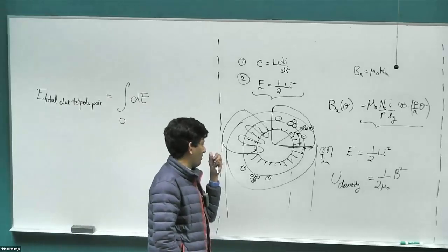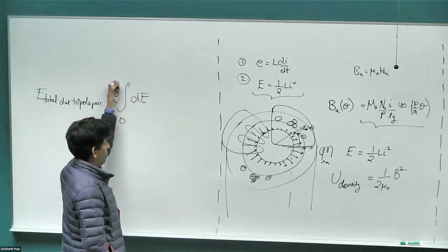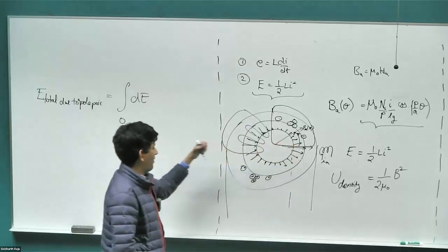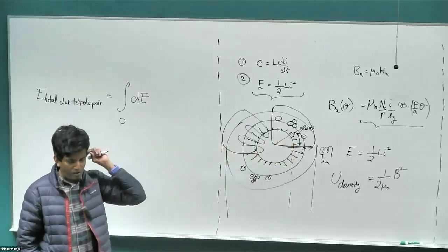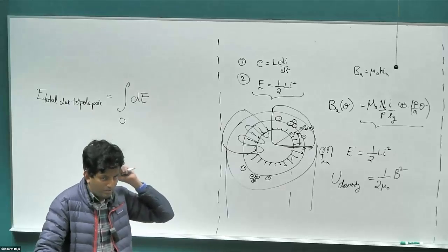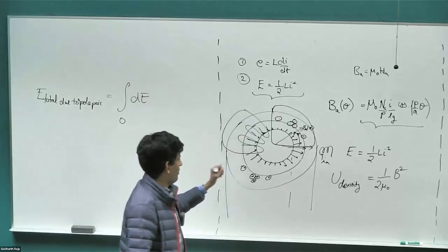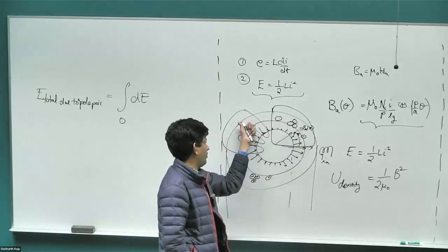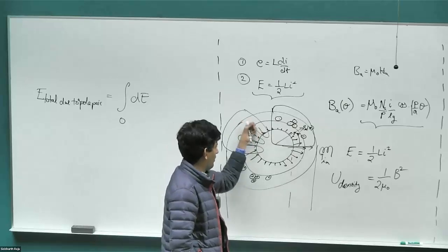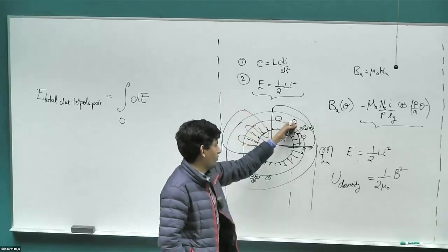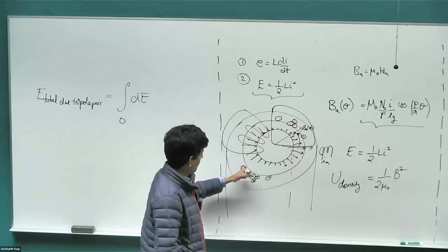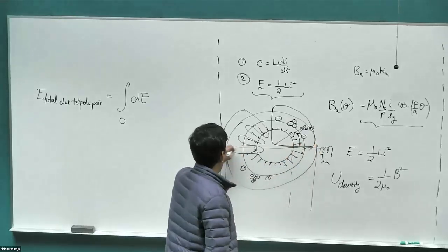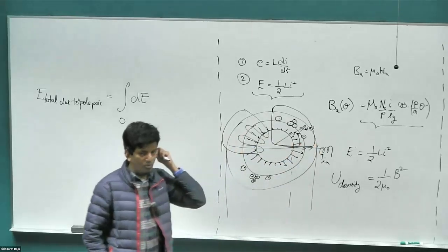Let's say in case of a two-pole motor, the integral is very obvious. I'll do from 0 to the full angle, 0 to 2 pi. If I want to do it for a p-pole motor, what would be my angle upper limit of integration? Because I just want to figure out what the energy is due to a set of coils. If I have this set of conductors coming out of the page and this set going into the page, their combined effect sets up magnetic field in the air gap, which goes in on one side and comes out of the other side. And then the other set of coils does the same thing. So all I'm interested in is what energy each of those coils contributed.